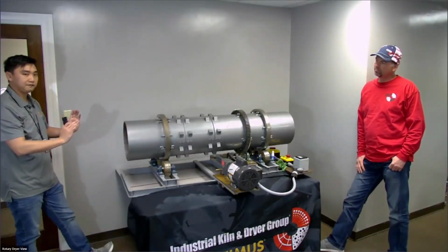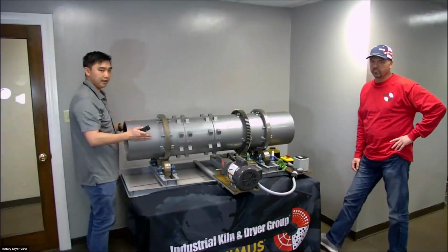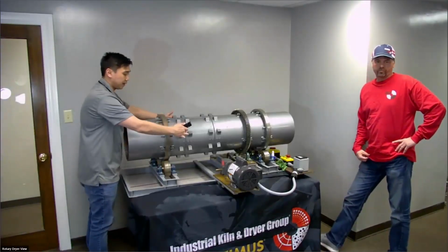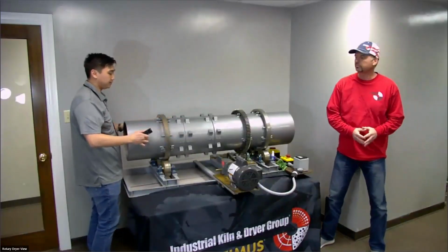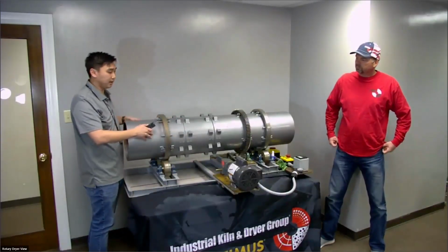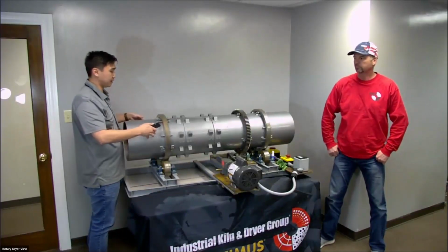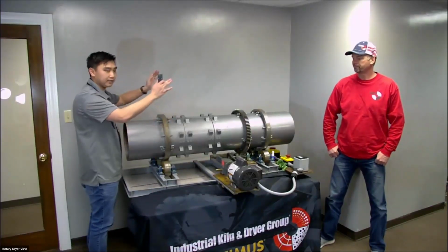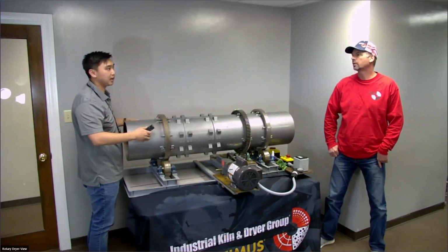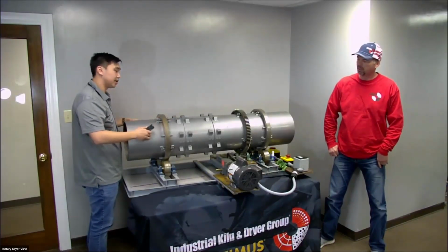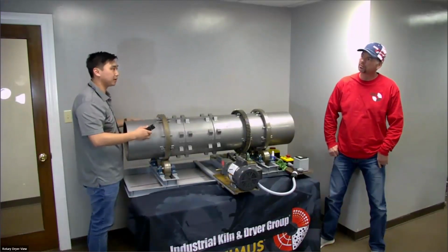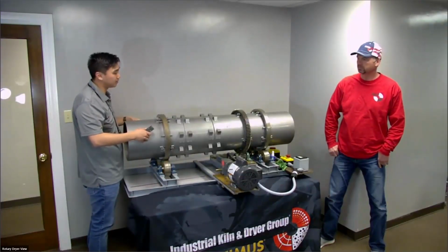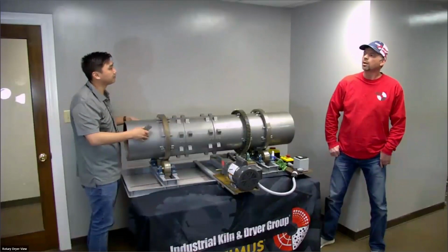If you have a direct fire, your burner's going to be in here. So this is where the combustion flights are lined up over here, right? That way you protect the shell a little bit. Now in a kiln, what's different is instead of combustion flights, you just have refractory throughout the whole thing. So that does the same job as combustion flights, except kilns are much hotter. You'll probably melt the combustion flights if you put them in a kiln, but the refractory will survive.